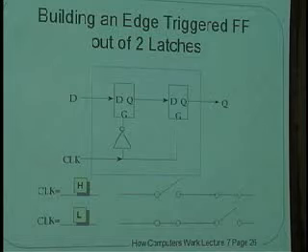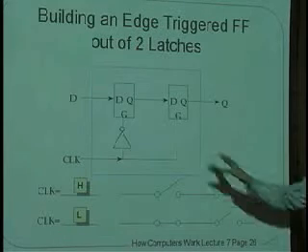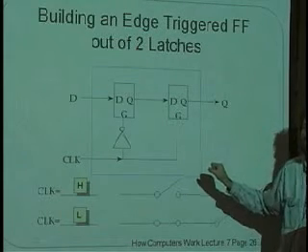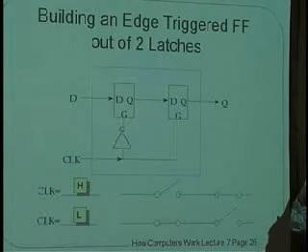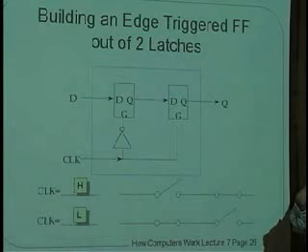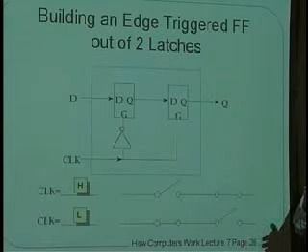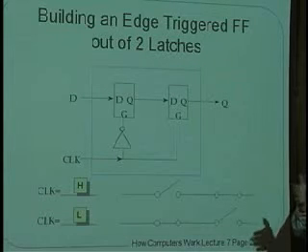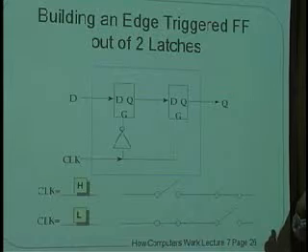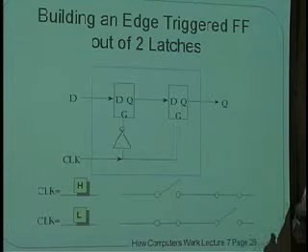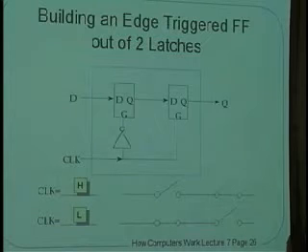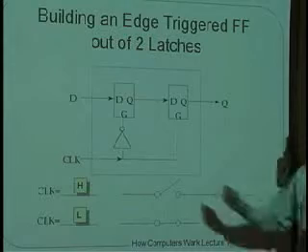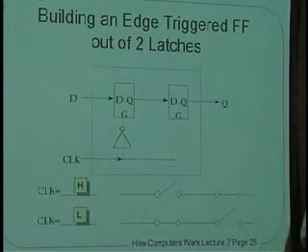There's another style of clocking where you sort of make sure one of these goes off before the other one goes on, as you would in an airlock, okay? If you have these two doors, right, and one's going to open when the other one is going to close, what you really want to do is you want to close both of them and then open the other one, close that one, and then open the other one, close that one. And so the design of the circuits on the inside, the designers are very careful to arrange the timing in such a way that it is never the case that both of the G's are high at the same time.